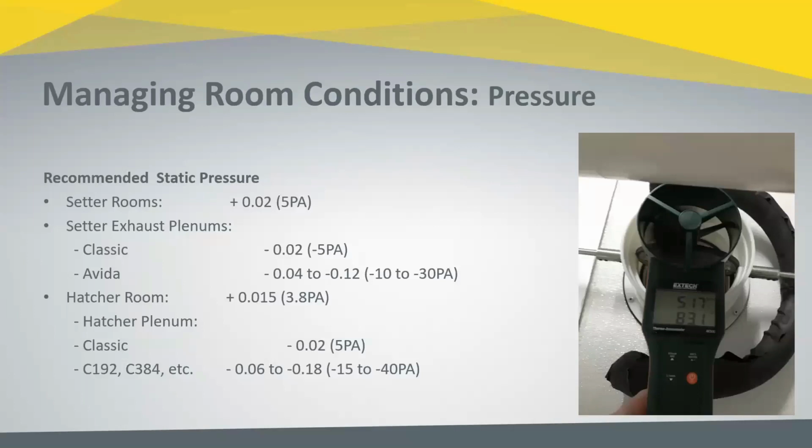The second question came in from Tolga saying, hi, Chad, people tend to set pressures to max, and I think there are some problems such as uneven EST when set to max. How do you think we need to decide what we need between -10 to -30 pascals? So in reference to that, Tolga, that's a great question, and thanks for that. The EST he was referencing is eggshell surface temperature reading.